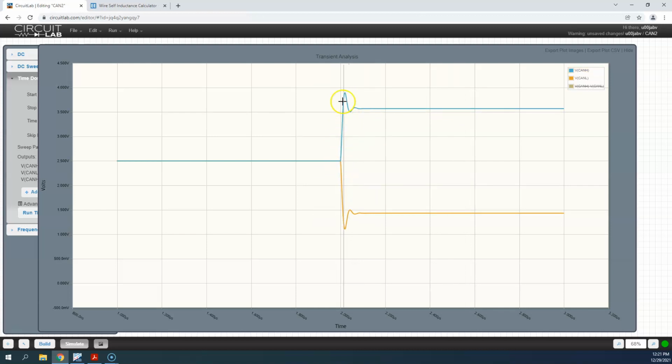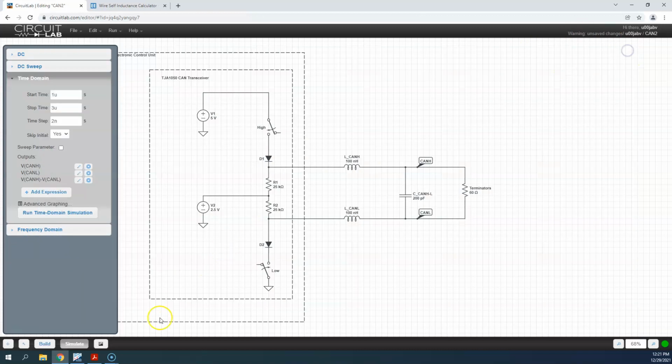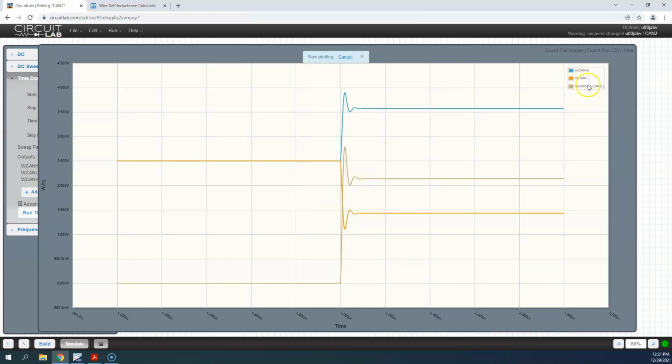So if I were to model this and take the J1939 cable, if I were to take all of these out, this would be virtually a vertical line in the time domain. So I run the time domain situation. If I took the capacitance and inductance out of it, it would look more like the ideal signal. But the real signal looks like this.